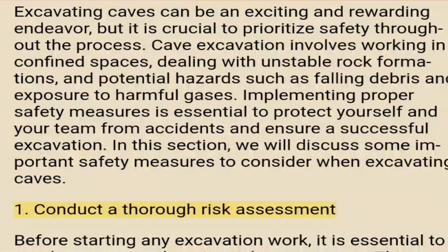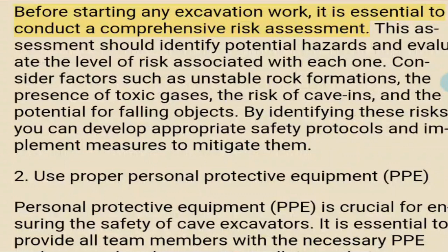1. Conduct a thorough risk assessment. Before starting any excavation work, it is essential to conduct a comprehensive risk assessment. This assessment should identify potential hazards and evaluate the level of risk associated with each one. Consider factors such as unstable rock formations, the presence of toxic gases, the risk of cave-ins, and the potential for falling objects. By identifying these risks, you can develop appropriate safety protocols and implement measures to mitigate them.